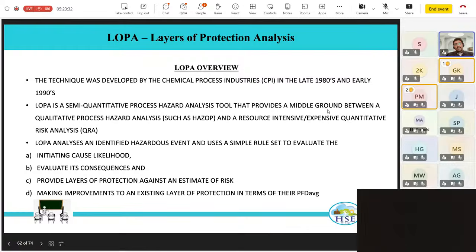There are different software, DNV, FAST, Safeti, you have Shell FRED, you have FLACS and ANSYS for 3D modeling, CFD analysis. So there is a different set of software. Those software are also exorbitant, and so that is why they are saying expensive quantitative pricing. Whereas the exercise is also expensive because many times the client comes back with sensitivity analysis to be done for such studies. Sensitivity in the sense of what happens if it fails at this point, what happens at this point. So our HAZOPs and LOPA can be completed in 2 weeks for the same quantum of work. This QRA would go on for six months. So that is why it is saying an expensive and extensive exercise.